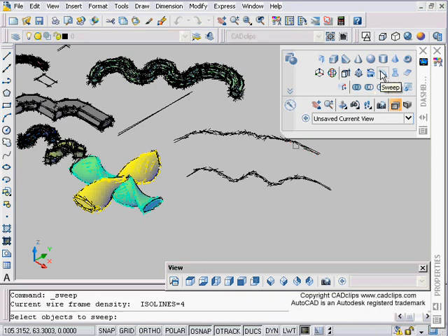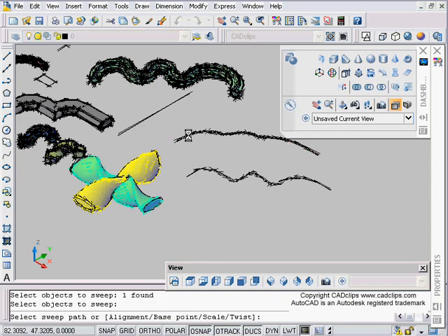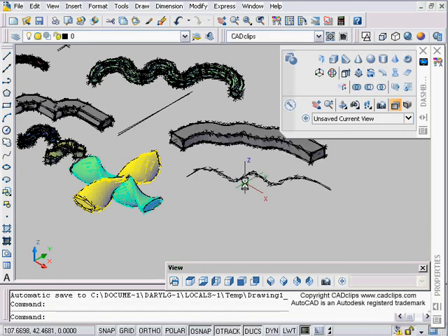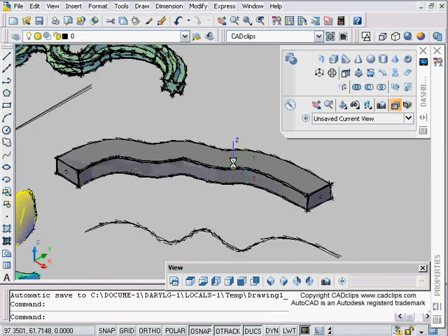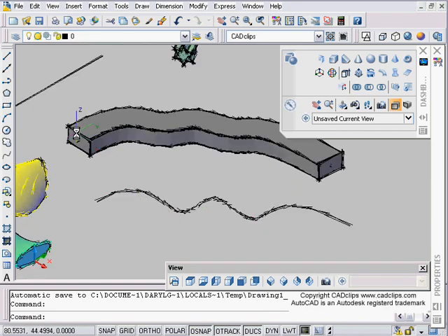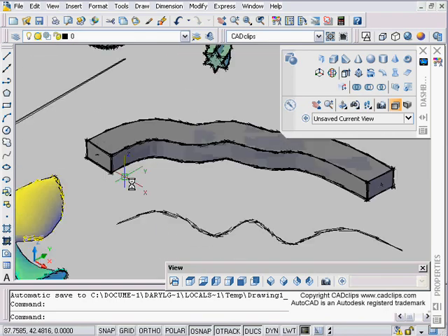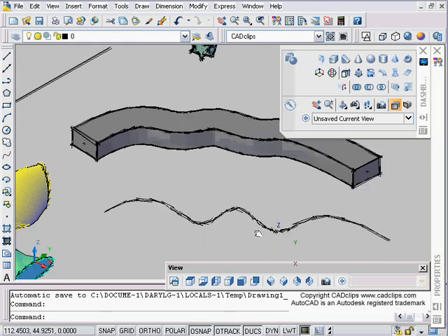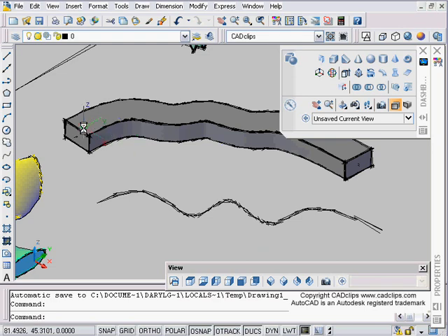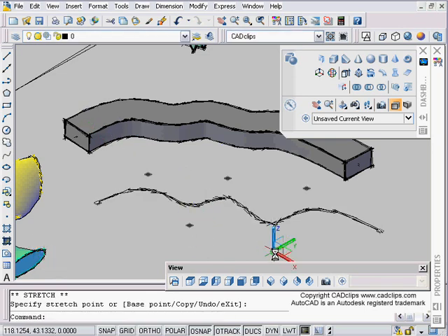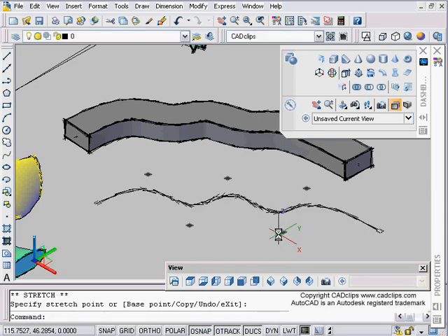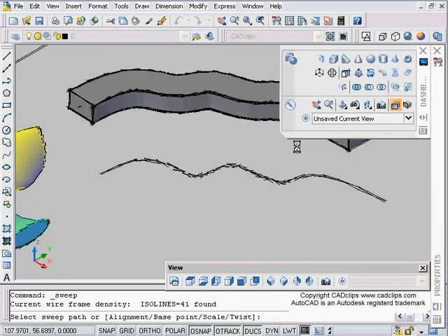What if we draw just a spline? Let's try this one more time to make sure. This, enter, here, and oh, that time it worked, interestingly enough. So the thing is, you have to be careful if this object is too large and it starts to actually interfere with itself as it goes around the corners. That's where you'll end up with a problem. So that may be the problem with this, is that those curves are a little too drastic.